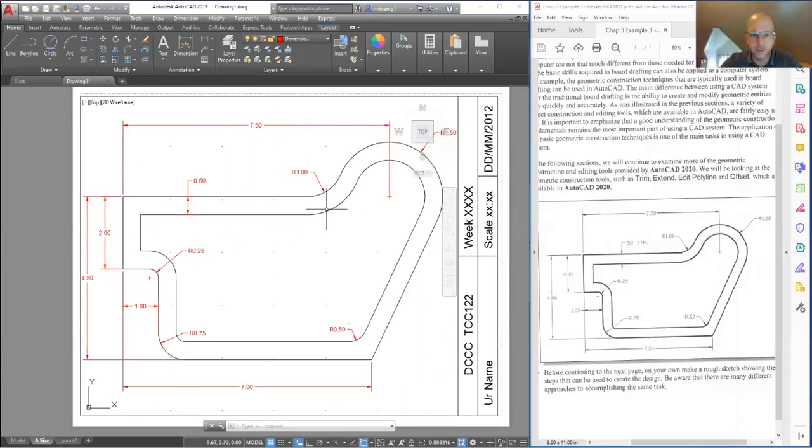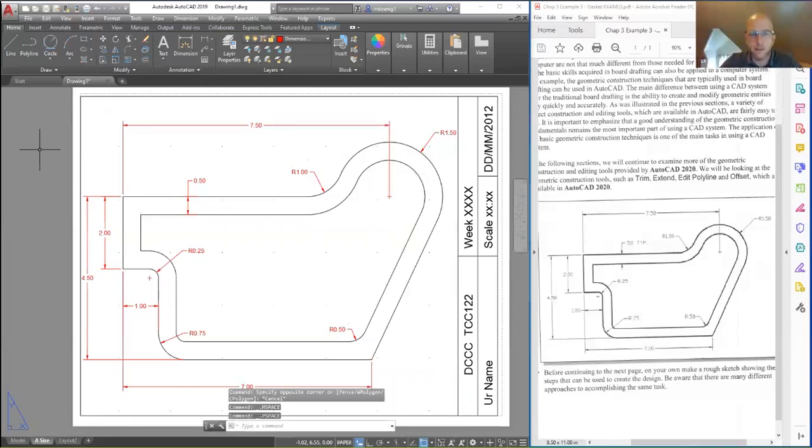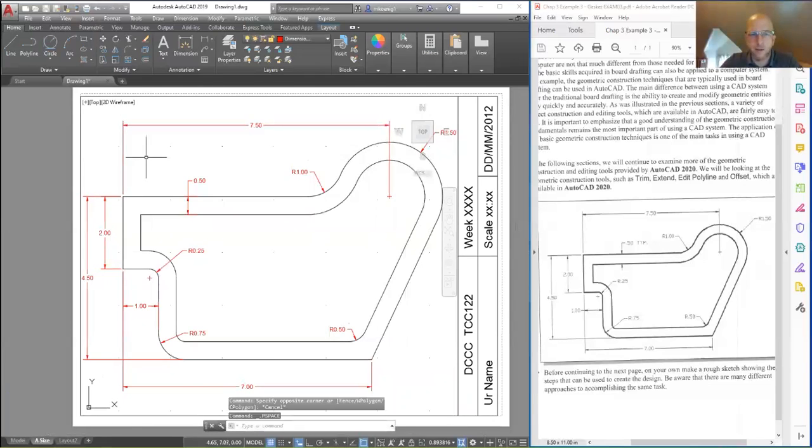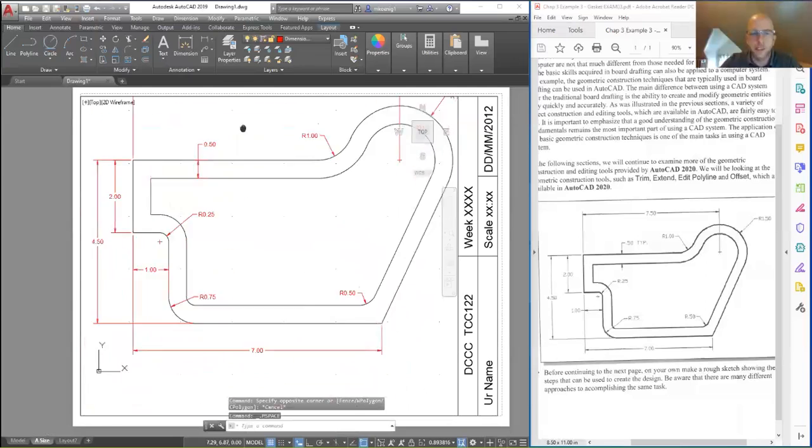So once you have it set in terms of scale and position, come back on the status bar to the paper space. So it should say paper there. Another way to toggle between the two is just by double clicking inside or outside of the sheet. So see how you have the view cube, navigation bar. This just means I'm in the model space.